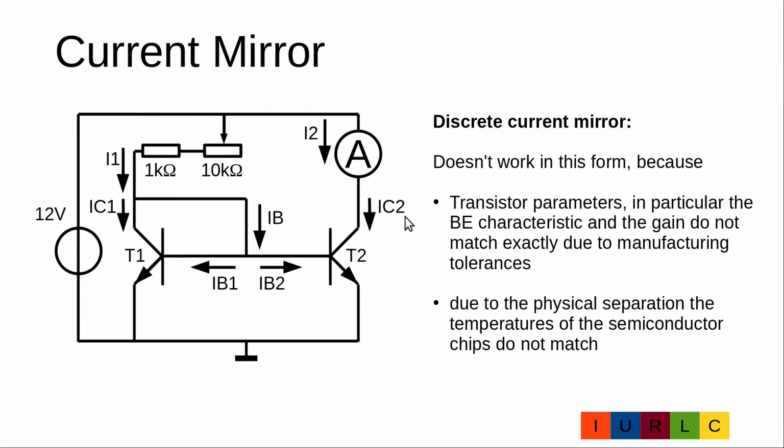With the bigger current and the high voltage drop, the transistor T2 becomes even hotter. The base emitter voltage will go down, and even more current will flow to T2 and less current through T1. And this will lead to a higher warm-up of the transistor T2. We will get a runaway effect, and if it is not limited by anything else, like in this circuit, transistor T2 can die.